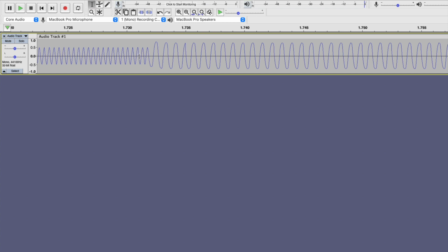The transition you see here is two 2400 Hz waves that together make a 1 bit, followed by a single 1200 Hz wave that makes a 0 bit. Even though I haven't implemented start and stop bits for every byte, I did need a way to synchronize the start of the recording, so I have 1 start bit for every recording.